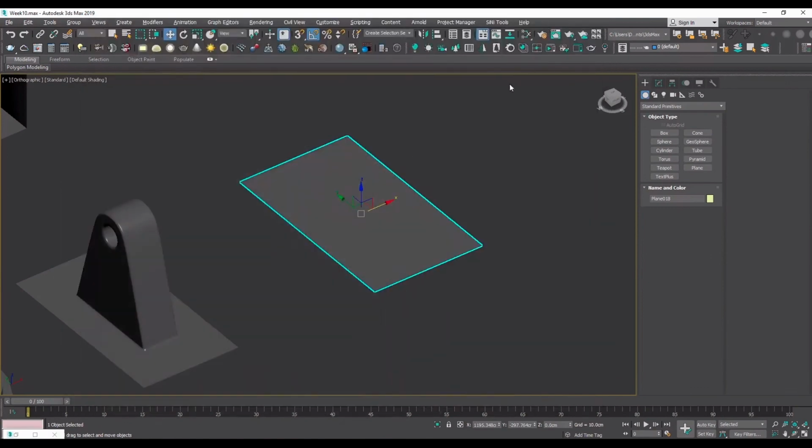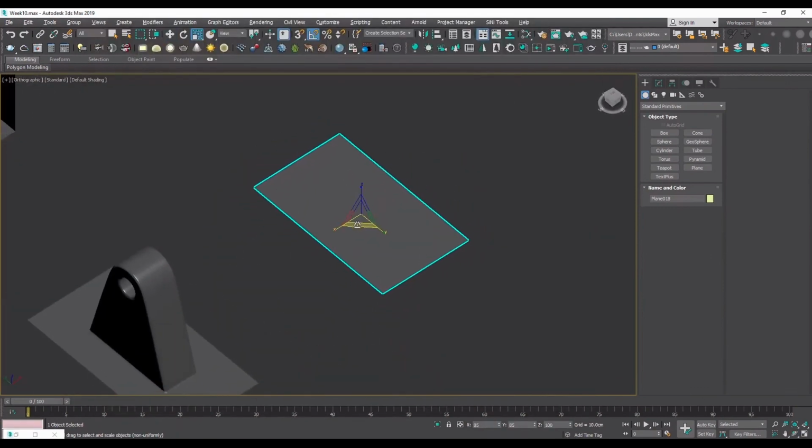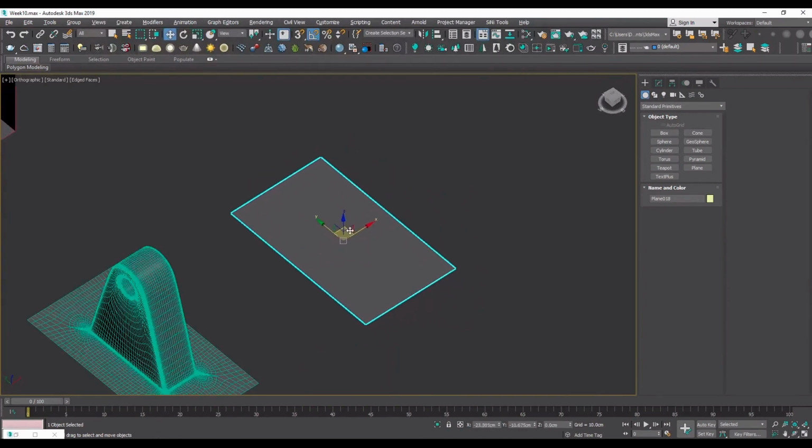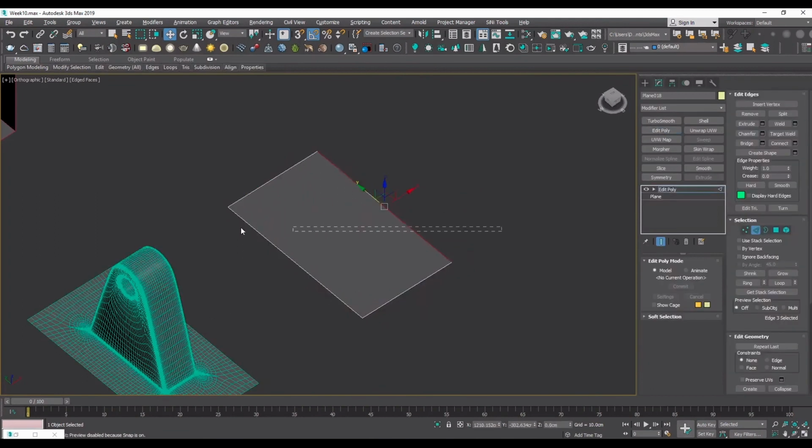And I believe you should know here why we have been choosing to create edge loops with the connect command rather than getting an inset to get the blockout done, because if we use the inset, we would get diagonal lines, and diagonal lines means, you know, a circular shape, not a rectangle shape anymore.